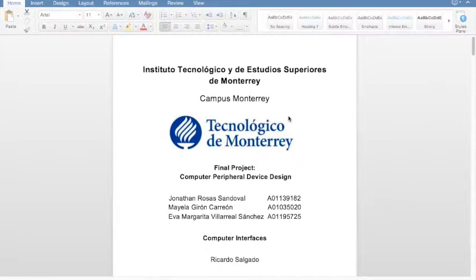We can conclude with this project the importance of the firmware and hardware design to make a working application, in this case data acquisition. To accomplish this, we define the USB descriptor, in which we establish the characteristics of the peripheral device, such as the device configuration, interface, and also information about the device itself, and the endpoint descriptors. Also, the way the information is meant to be read by the computer and by the final user of this application.